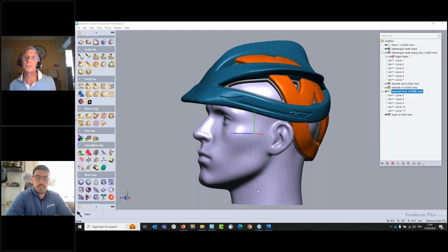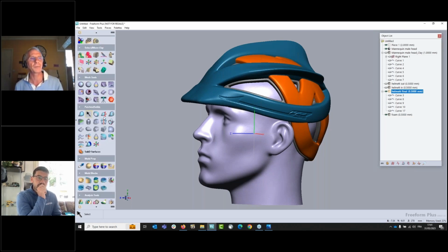Freeform Plus will allow you to go more deep in some details. For example, in Freeform Plus, you have some mold capabilities, which allows you to check for the undercuts to be sure this object can be molded or not. You will also have the ability to create some patches, and solid to export this model as an IGS file, step file, or a Resolid file to continue or to finish the design on a CAD software.